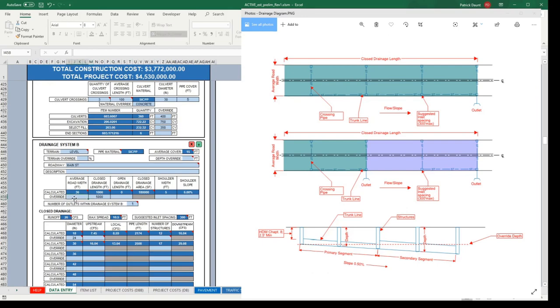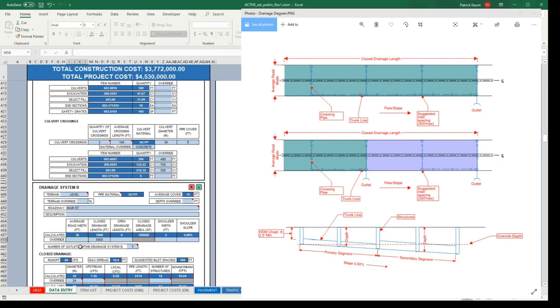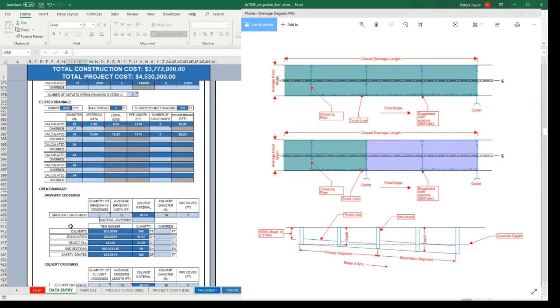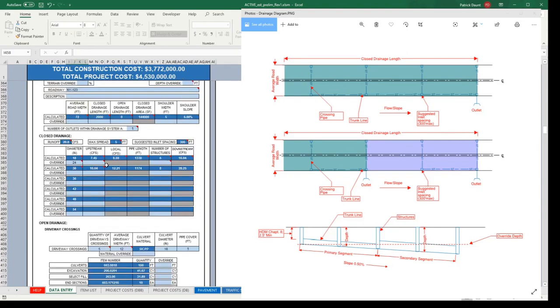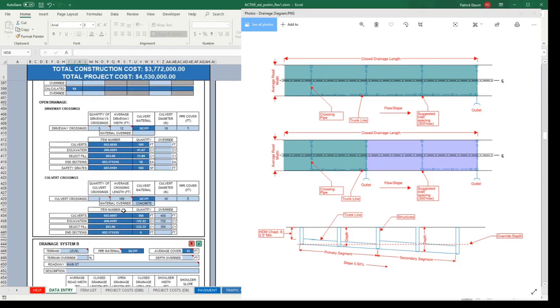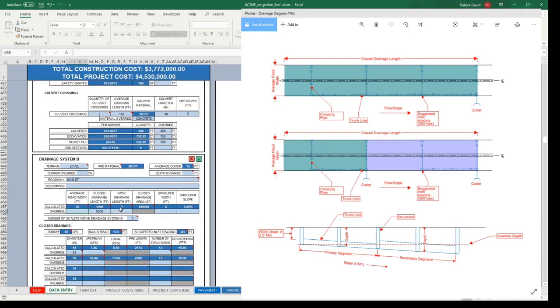So keep in mind that this is only a 36-foot wide road compared to a 72-foot wide road. So it takes a lot more distance in order to exceed the area that a 24-inch pipe can handle. So 5,000, 36, 180,000 square feet. All right.